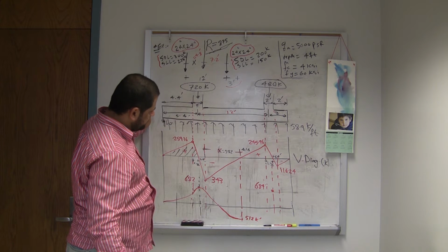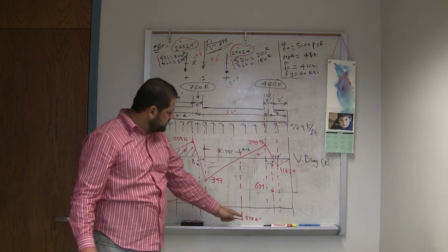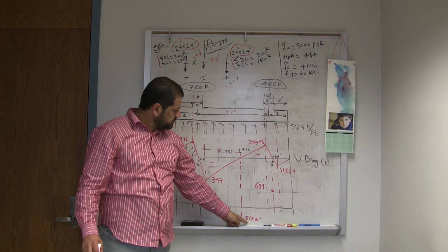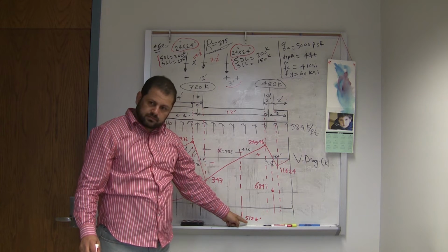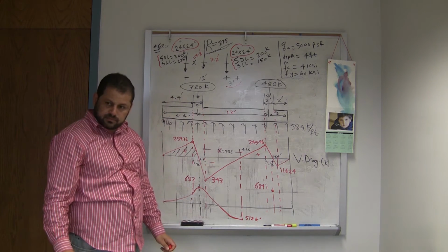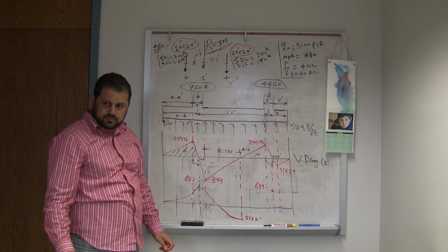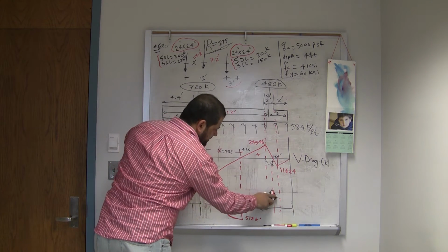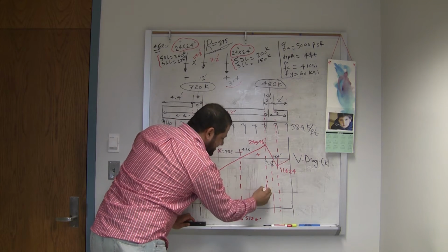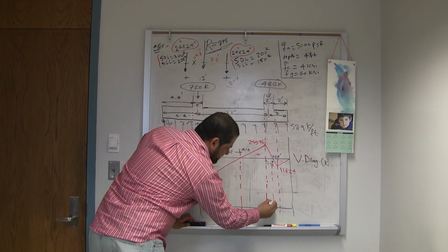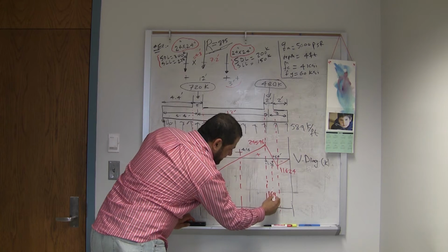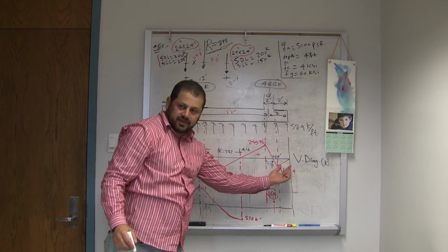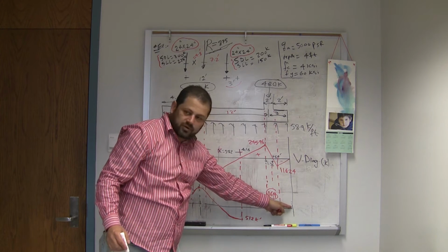Are you sure about that? Did you subtract this from it? 1.88 plus 1.36 times 245.96 over 2. Oh, actually, yeah, you're right. Sorry, I forgot to subtract. It's 169. So this one will be 169, 169 in here in the column. Now this will give you 169, so the moment diagram will close.